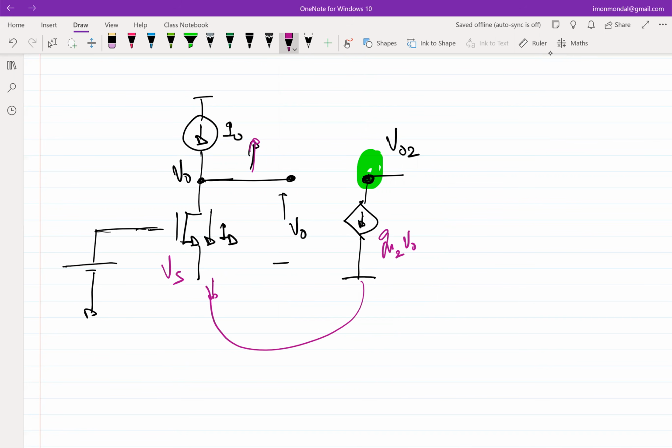First, the sense of the feedback is not right, because if you break the loop anywhere, let's say I break the loop at V naught, and I increase this voltage, then what is happening? You are pushing current into Vs, which means this is increasing, which means this further will increase. So this is positive feedback, right? So this clearly will not work.